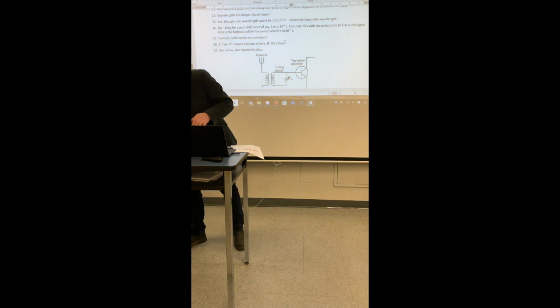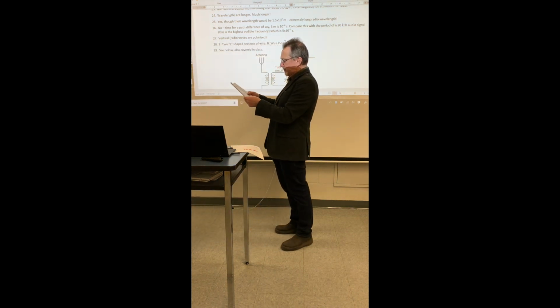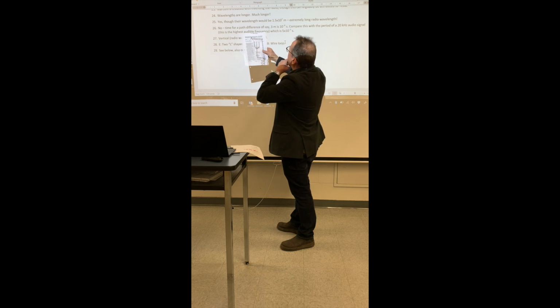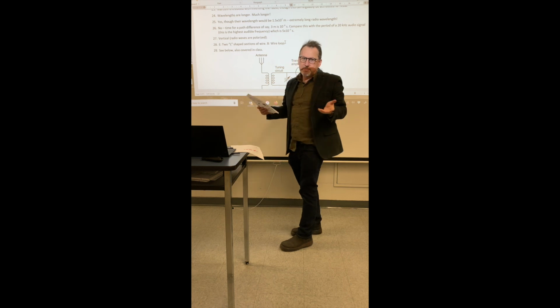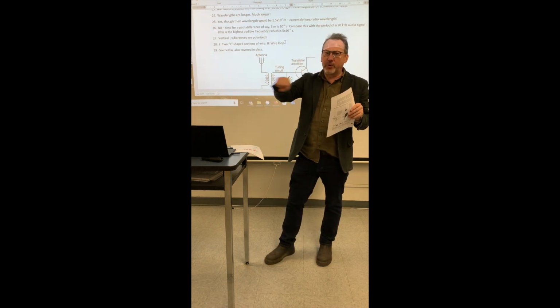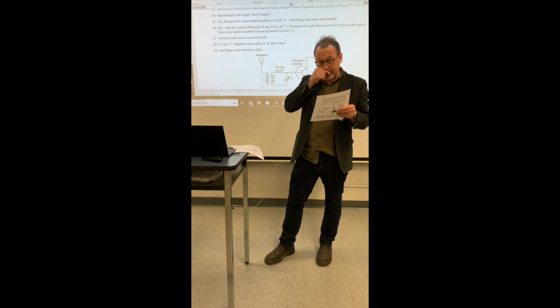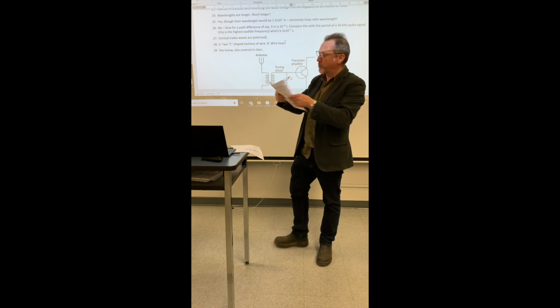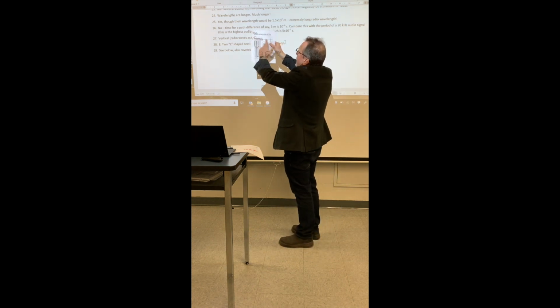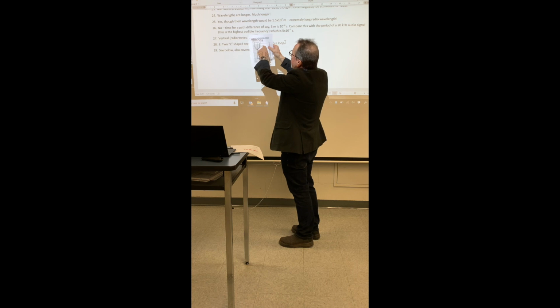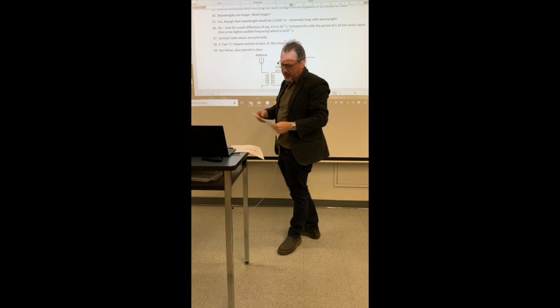Let's have a look at that worksheet again. This is really the answer. The coil of wire detects the magnetic field, whereas the rod like this would detect the electrical field. Just imagine we had the experiment where we pushed a magnet through a coil that produced a voltage. The magnetic part of the electromagnetic wave goes through this loop of wire and produces a voltage. So the loop of wire detects the magnetic part, whereas the horizontal bar detects the electrical part of the signal.